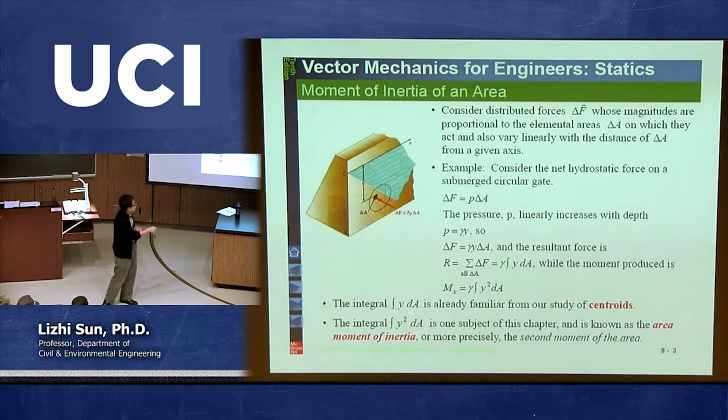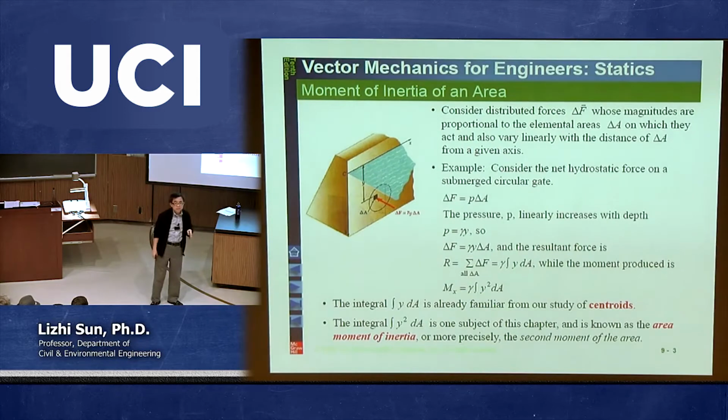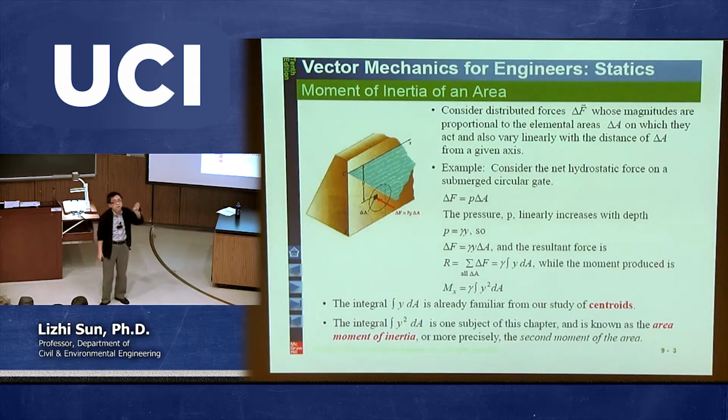See, this unit is fundamentally different from the moment we talked about in chapter 3. Because in chapter 3, if we need to calculate the moment, the unit must be force times distance. In other words, it's going to be Newton times meter. That's the unit of that kind of moment we talk about. But now, this moment of inertia is basically a geometry concept. It's just basically the integration of Y squared dA. And then how we're going to integrate depends on what kind of area we're talking about. Okay, which I'm going to show you with some examples later on.